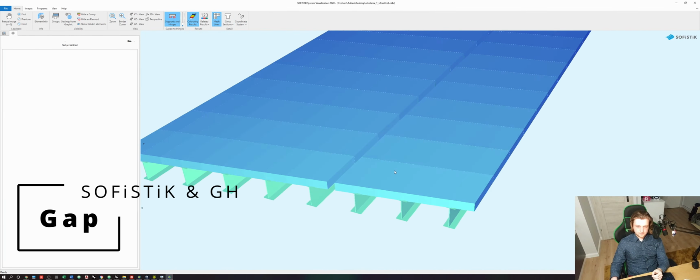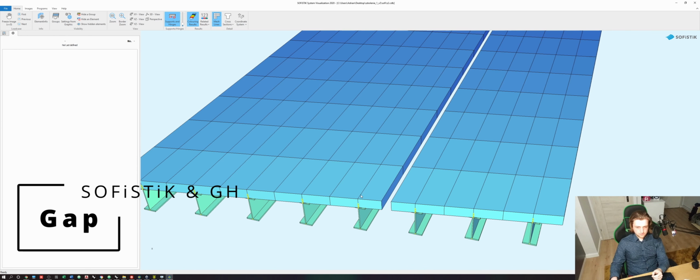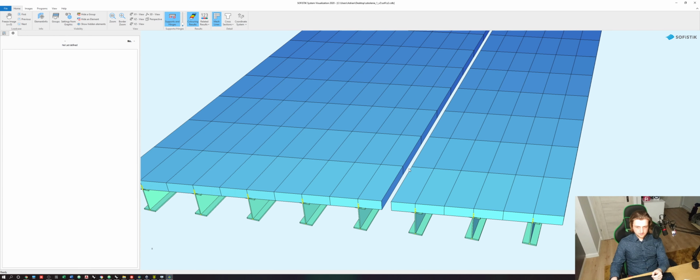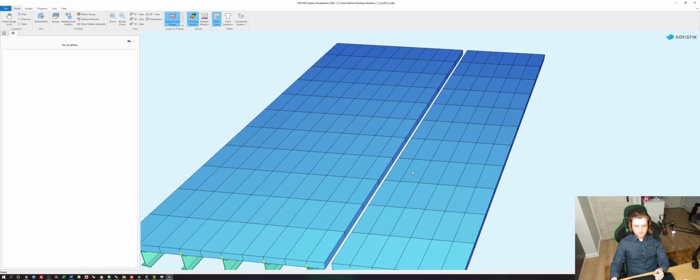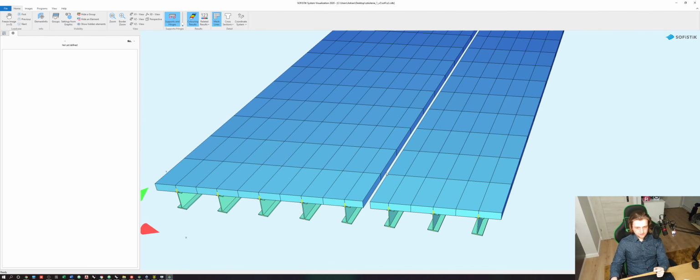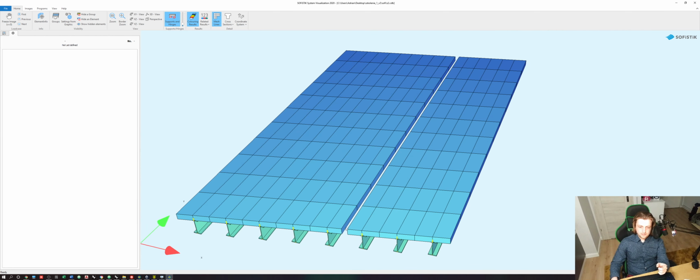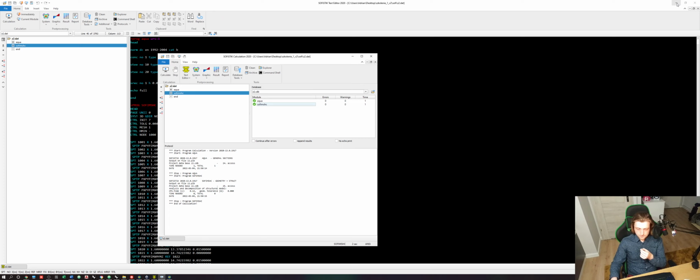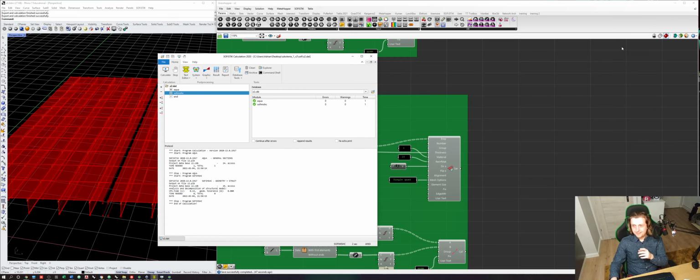Fantastic. Now we have to only create this fulfilling of this gap. So for this purpose, we have to get the interior edge of the first part and the interior edge of the second part and divide it in the same division as we have done it previously, and connect it by the 4-point surface component. A 4-point surface component. Okay.